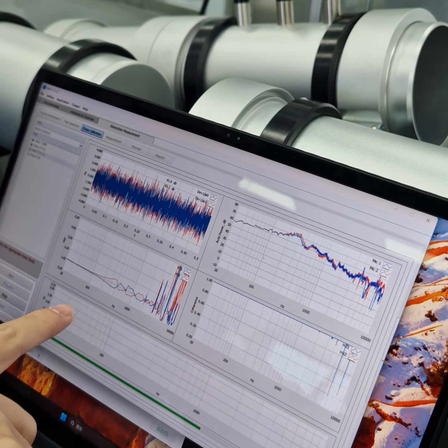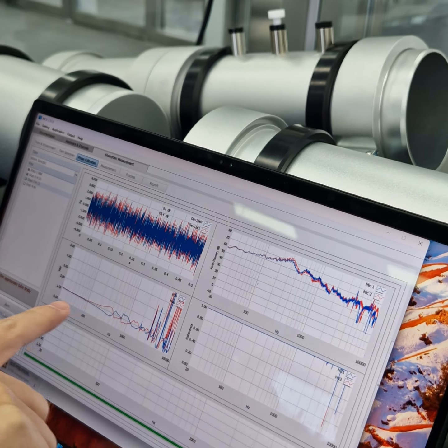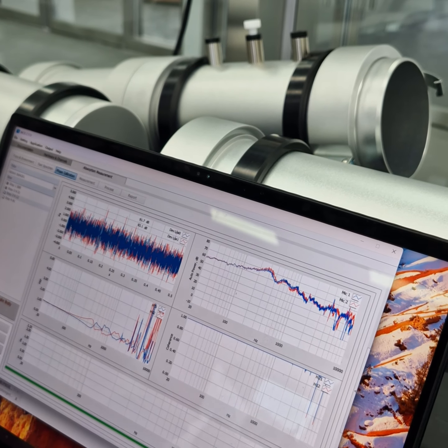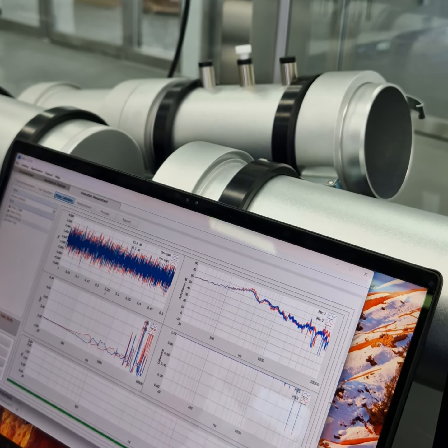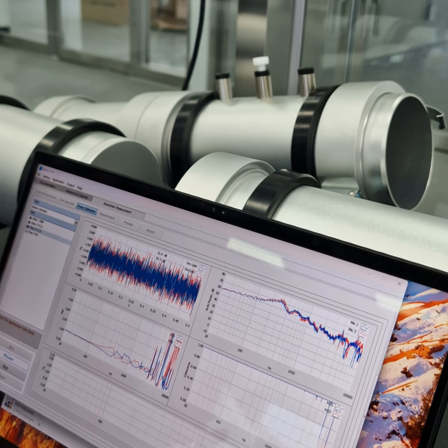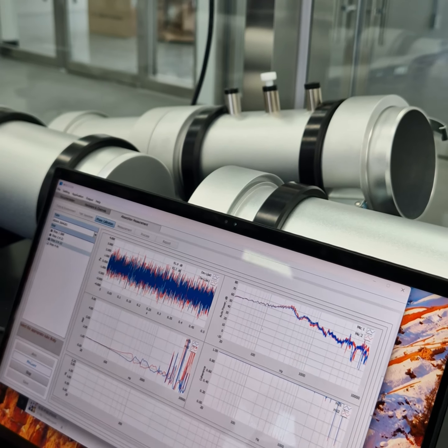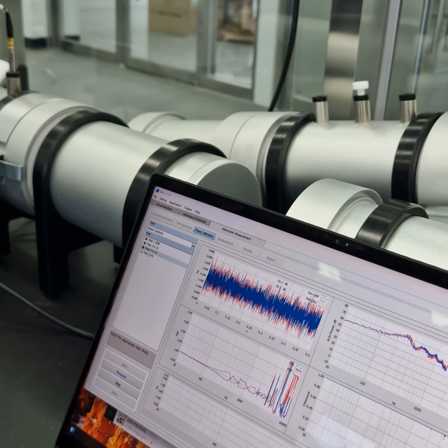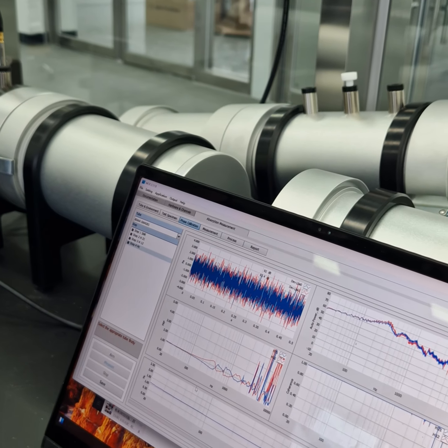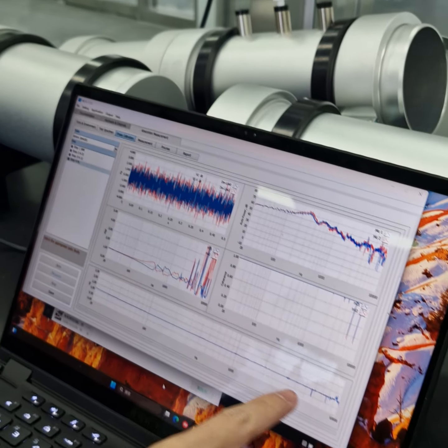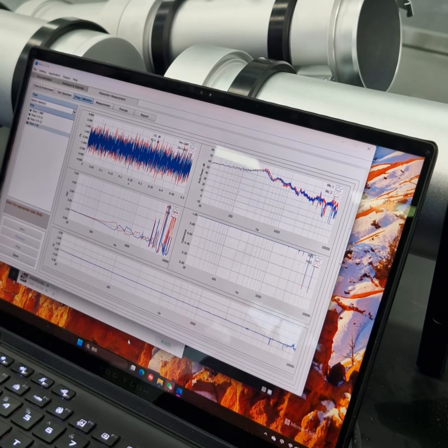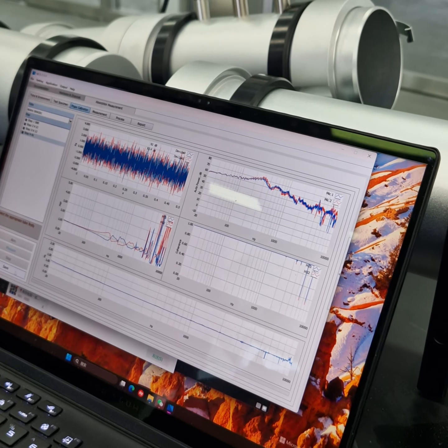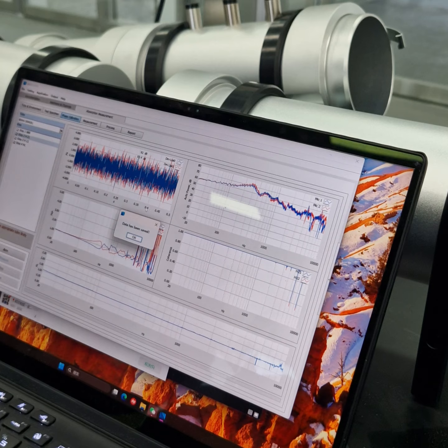Based on this transfer function, it will calculate a factor that can correct the phase. So it's called phase calibration. After all these tests, you will go to calculation HC. It will automatically calculate the HC for you, the correction factor for the test, and then you need to click save. Remember to click save. Okay, the data have been saved.